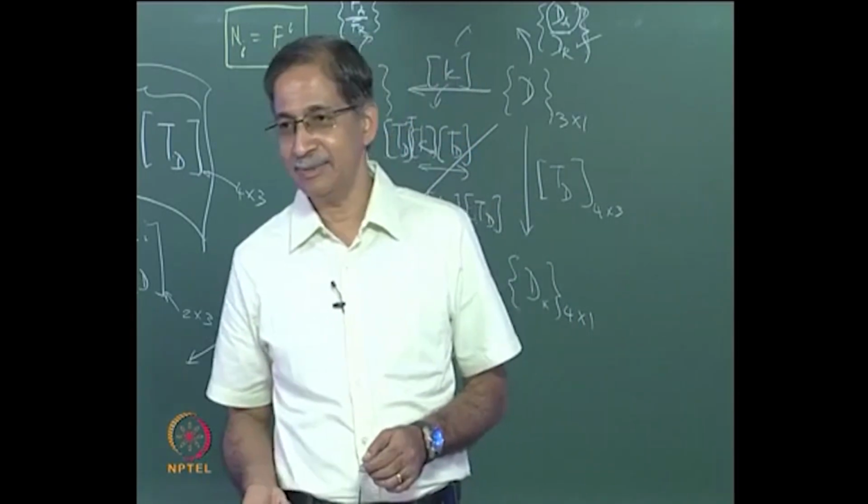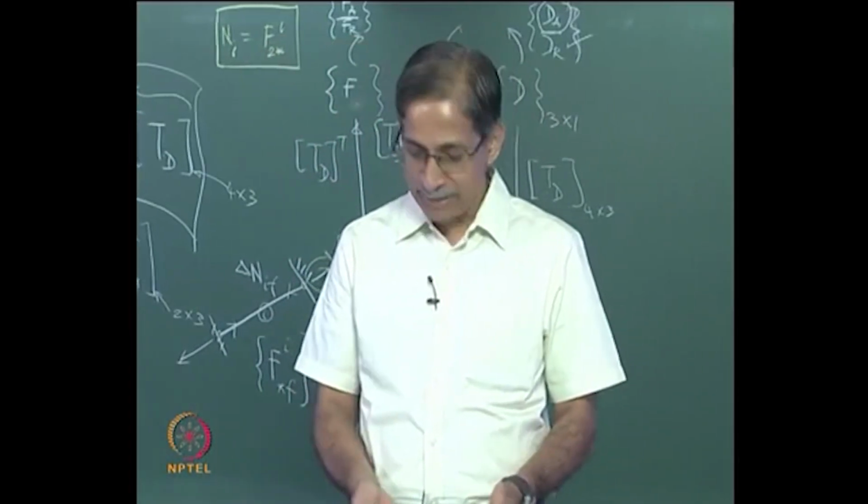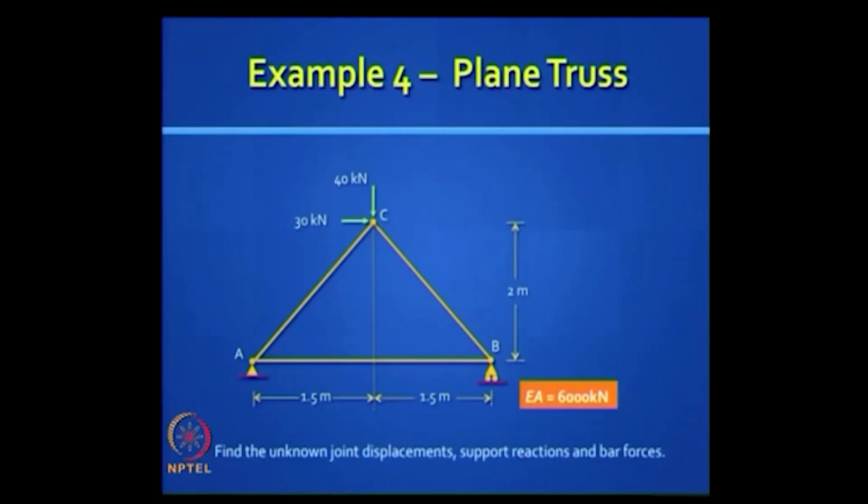We will take trusses. Okay, we will take a simple truss to begin with. If you had to do this problem, which method would you normally do? First, what's the question? To find the bar forces, what method would you use? You will use a force method. Why? Because it is statically determinate, you know the answers, and you can also use the principle of virtual work, the unit load method, to get the displacement.